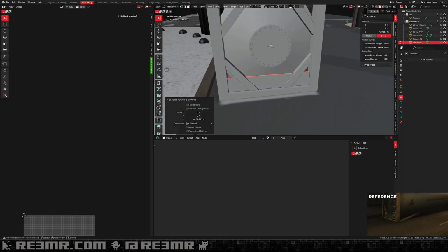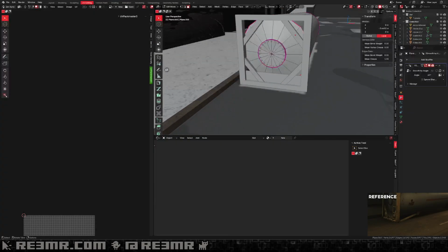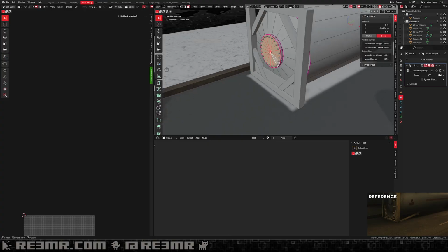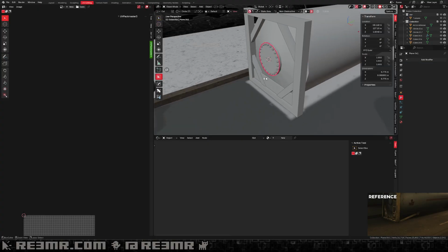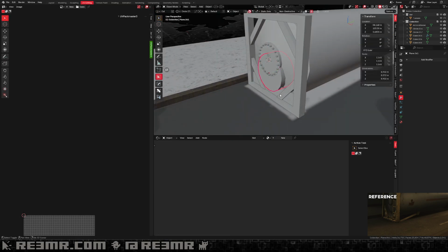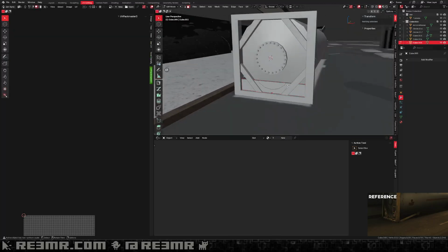At this shape here. To do that, I guess I could just grab this. Same thing again, press 4 to get the smart face thing. Pull this down to about here. Make it a bit bigger, I guess. Extrude, use that as a cutter object and cut a hole.